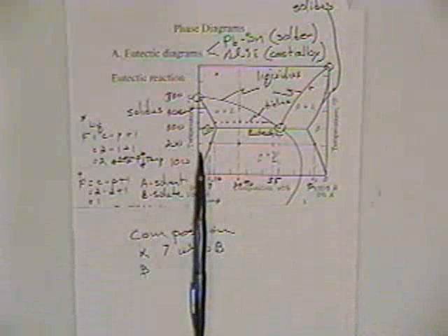What do you mean dissolvable? Well, you take water, add sugar to it. What happens? Shake it up, the water's clear, the sugar's dissolved. Those of you who have made iced tea know that if you add sugar when the iced tea's hot, what happens when you cool? Well, if you put a lot of sugar in, you start to get cloudy. That's because it exceeds the solubility limit, starts precipitating out. So up to 7% at this temperature of B is soluble in A.